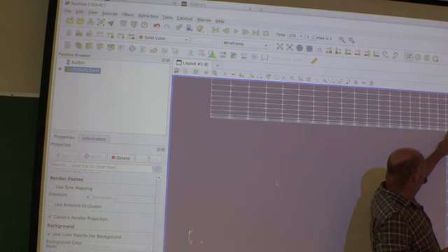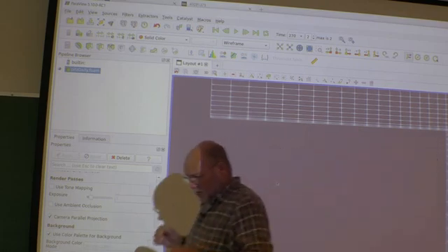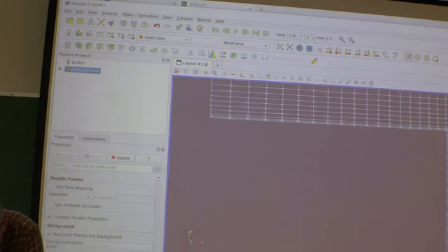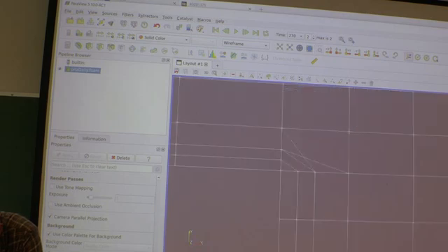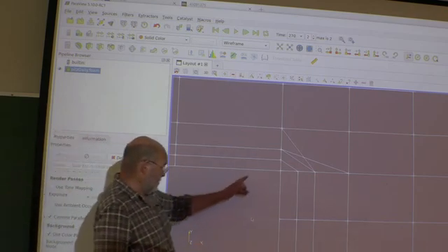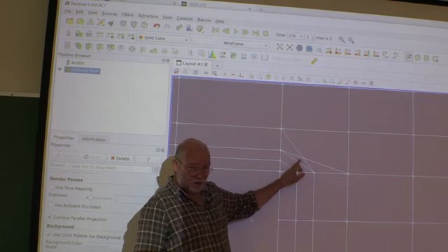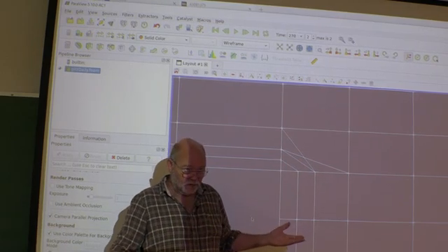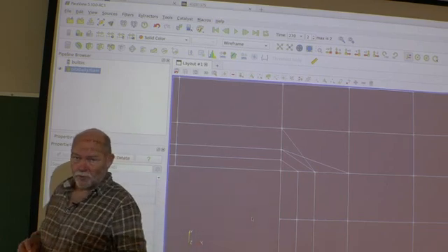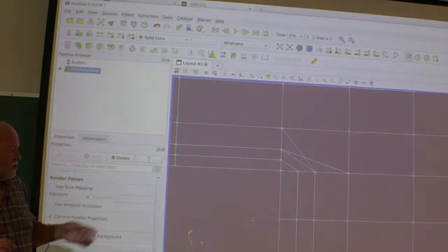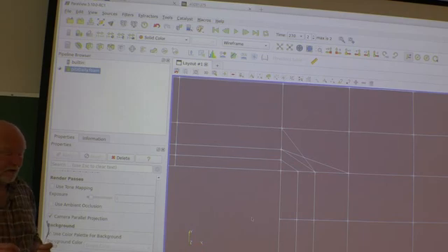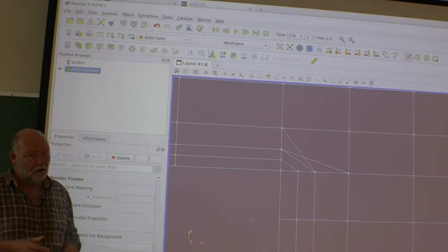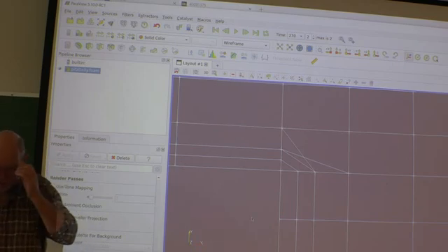And also sometimes you get some strange effects from this refined wall layer. Have a look at the corner up here. What the heck is he doing here? Making some very strange cells. If you overdo this, then here you risk having an area close to 0, and then he won't run. Then the check mesh will fail. So it has to be used with care, this refine wall layer. But since it's such an easy way to do it, it can be worth noticing.